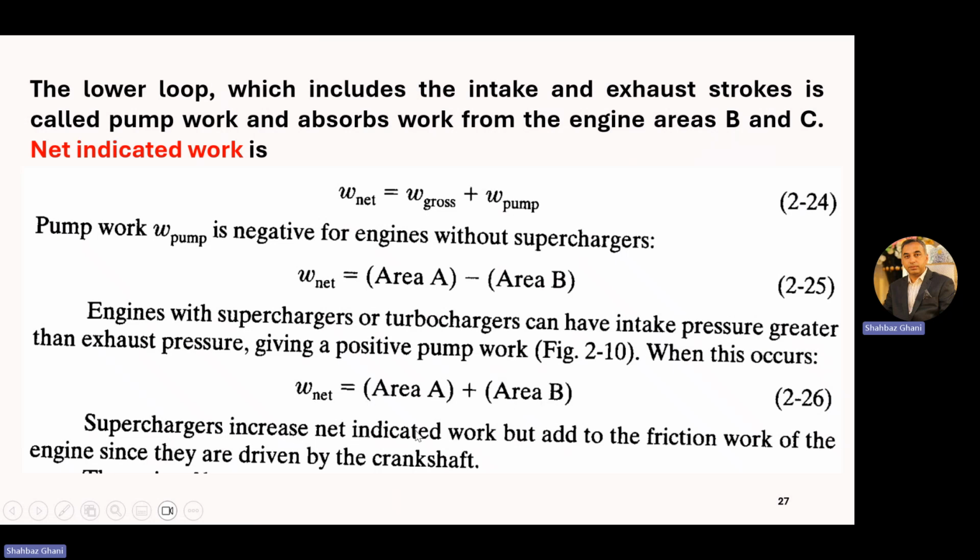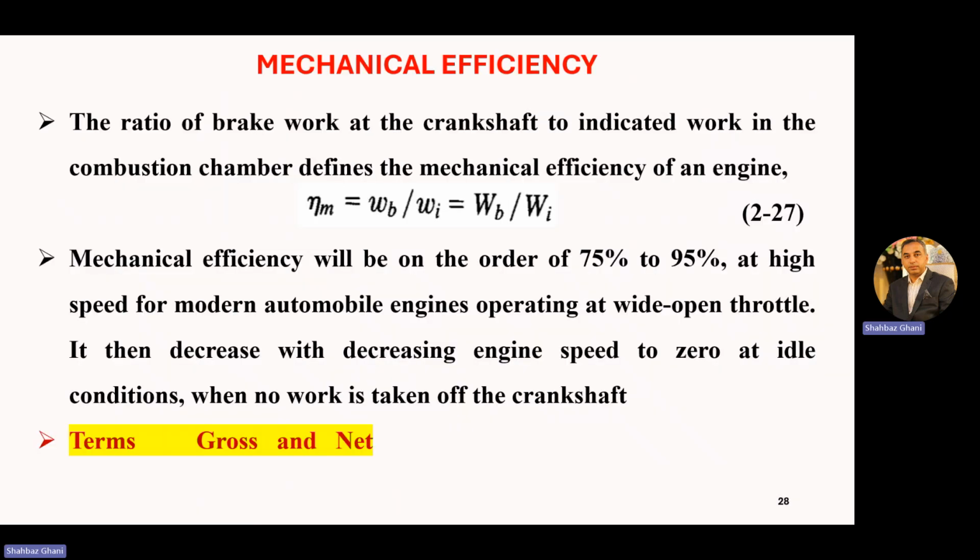A supercharger increases net indicated work, but it adds to the friction work of the engine since it is driven by the crankshaft. Remember this. Now, mechanical efficiency, another factor. First, we have discussed the work parameters. Now, the operating characteristics: we have the mechanical efficiency.